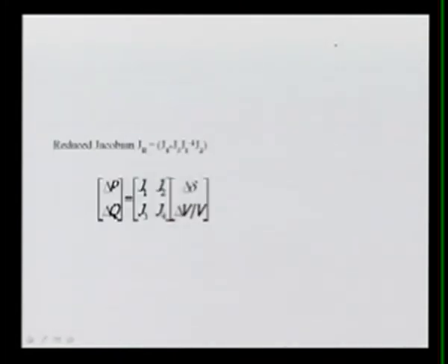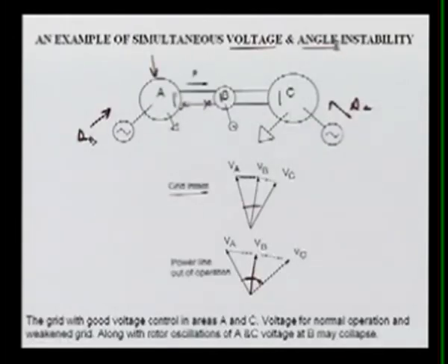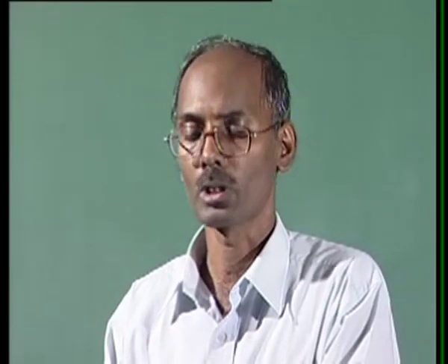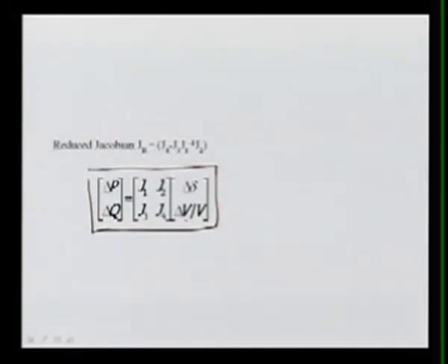Normally for this analysis, we analyze the reactive power with the load flow Jacobian. These are the Newton-Raphson power flow equations that we solve in polar coordinates. Here again I want to give a brief about load flow. Now the question arises: why are we using del V by V, why not V? The mismatch vectors for power are the change in real power and the change in reactive power. We go for the Jacobian matrix.